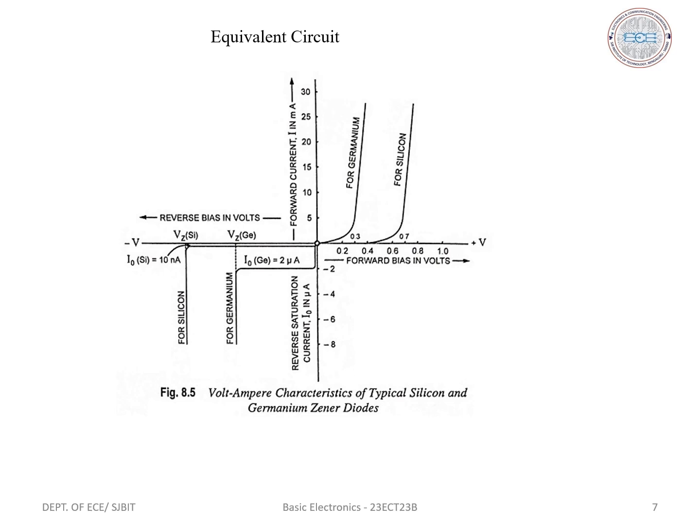In this region, the voltage across a Zener diode remains constant, but current changes depending on the supply voltage. So the above figure shows the VI characteristics of a Zener diode, where Vz is the Zener breakdown voltage, Iz minimum is the minimum reverse current to sustain breakdown, and Iz maximum is the maximum Zener current limited by the maximum power dissipation.